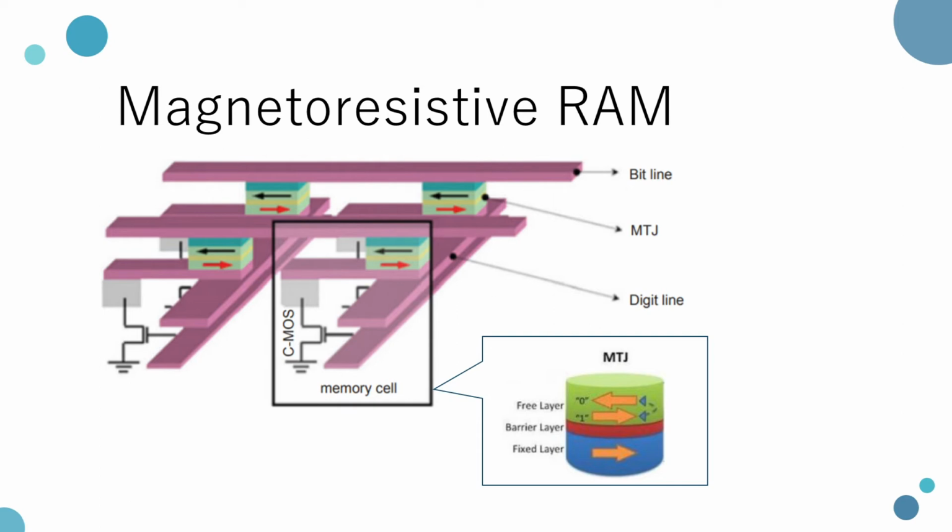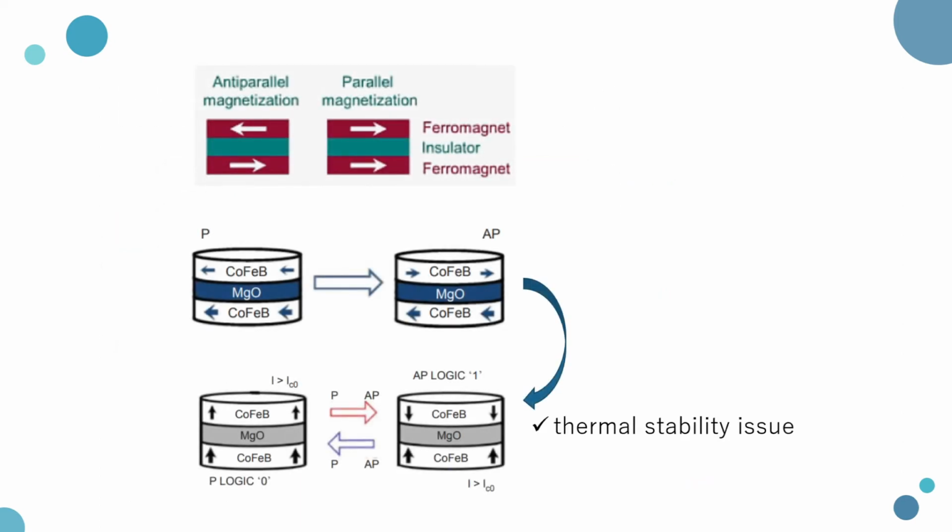As shown on the slides, this structure is a famous example of a magnetic tunnel junction. There is an MgO insulator sandwiched between two ferromagnetic materials made of cobalt iron boron. We can see that when the spin is parallel, the recorded signal will be 1. On the right-hand side, there is an anti-parallel configuration, which means opposite spins, so this signal will be 0.